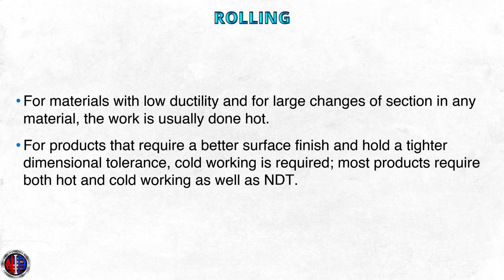For materials with low ductility and for large changes of section in any material, the work is usually done hot. For products that require a better surface finish and hold a tighter dimensional tolerance, cold working is required. Most products require both hot and cold working, as well as non-destructive testing.